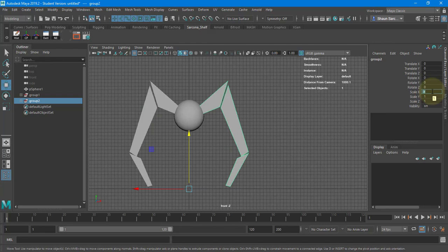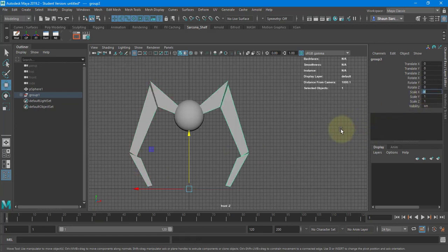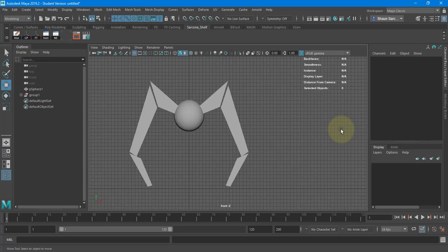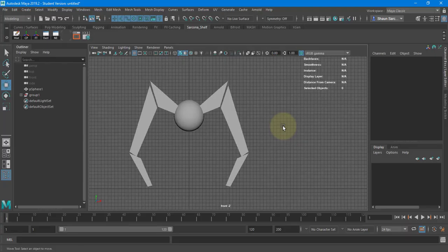And it pops it onto the other side. Okay? So a lot of times, very quickly, because everything is kind of on that side, we delete that. I'll just go Control G, Control D, -1, and there it goes. Okay? As you get quicker at this, it'll just come to you. So that's kind of cool like that.